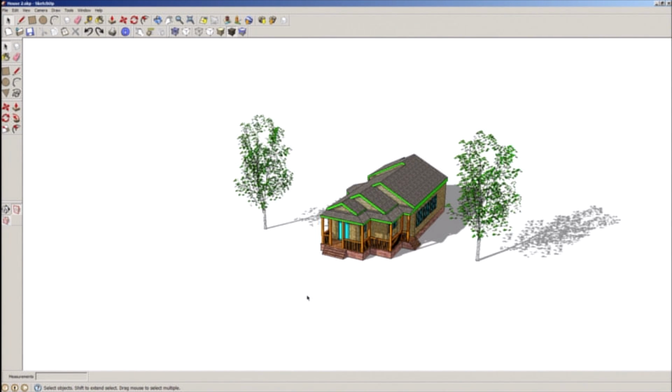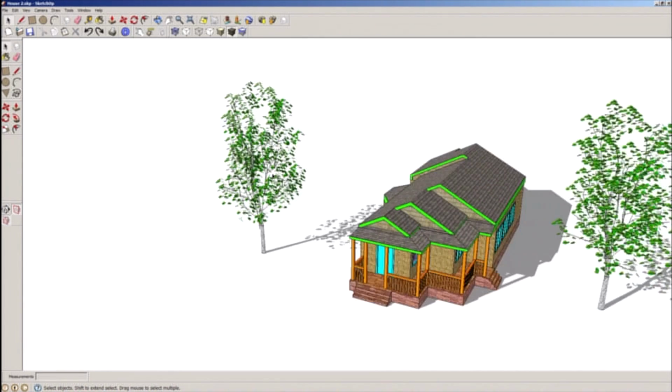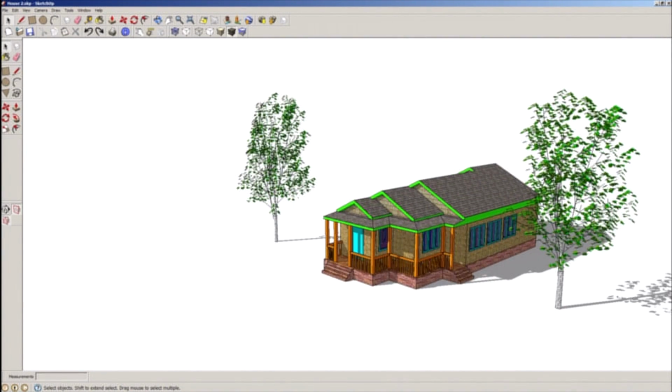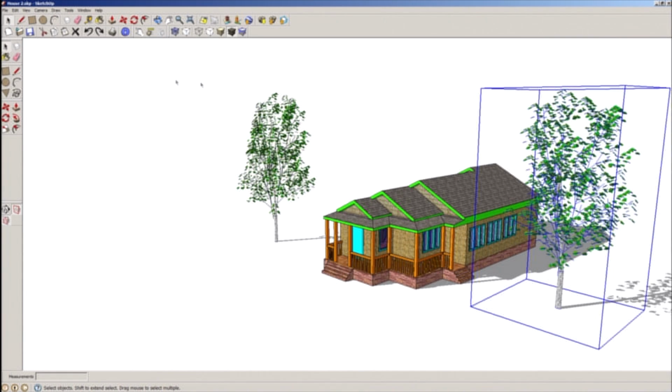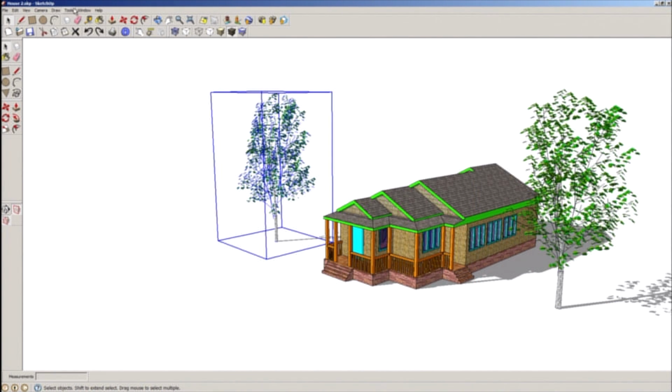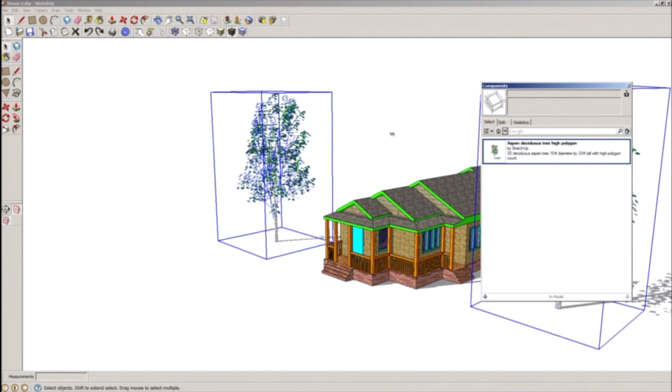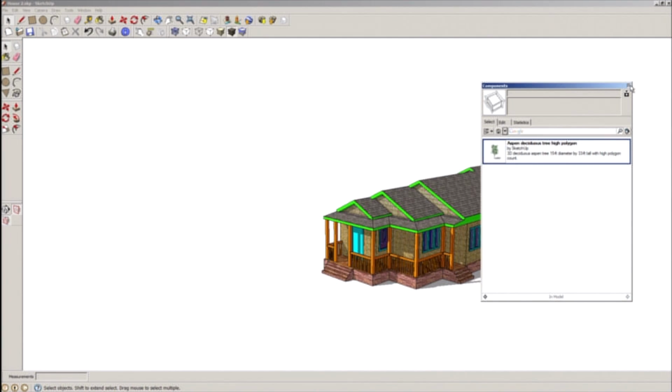So now that we know our two categories, we know we want to get rid of complex objects, and we want to get rid of geometry that functionally we don't want, we can get started on our destructive edits. For this scene, for complex objects, all we have are these two trees that I've placed in here for the purpose of this demo. What I usually do here is I go to Components in Model, right-click, select Instances, and just delete. Very quick, very easy.